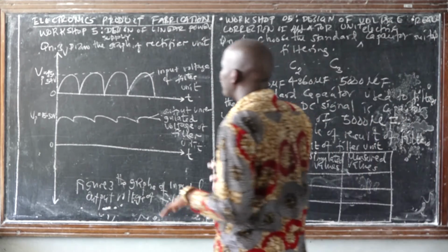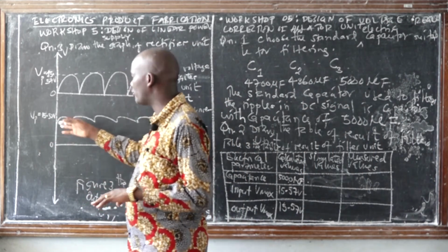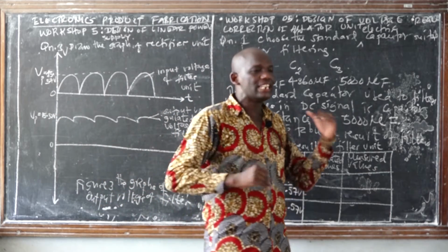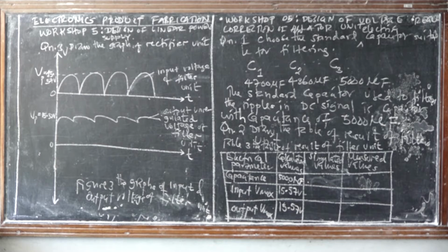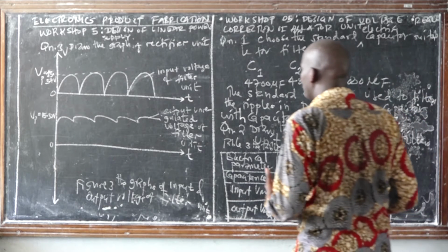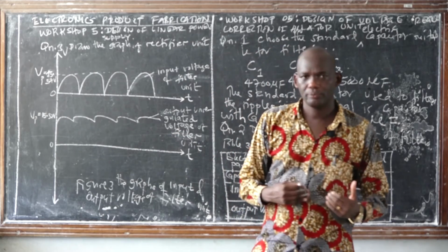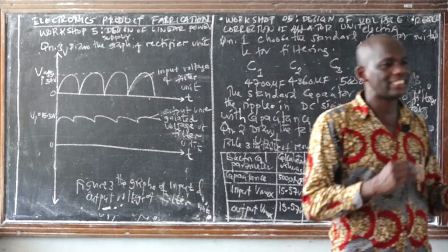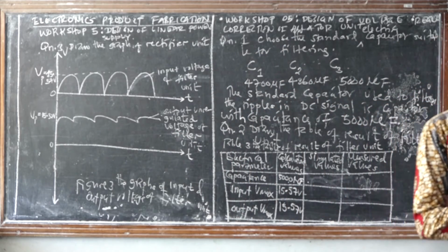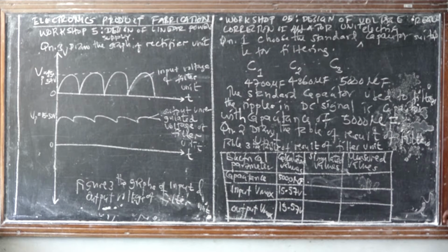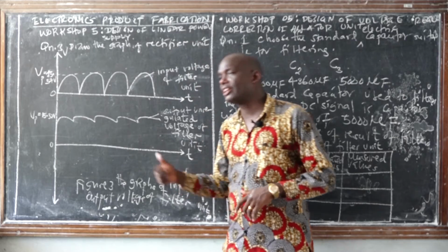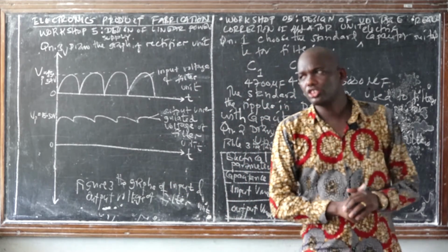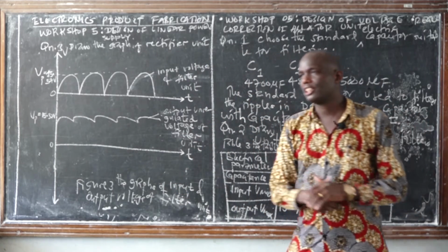Don't worry about the magnitude, whether it is 15.57 volts or whatever, but the nature of the signal, because most electronics and telecommunications components or systems need constant, regulated power. If the power alternates, most of the components might malfunction. That's why the output of the filter is still not convenient to feed directly to the load.